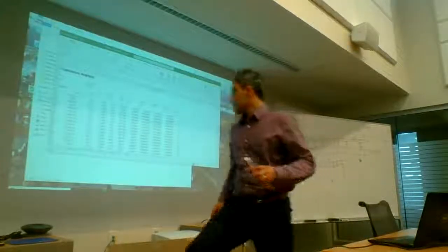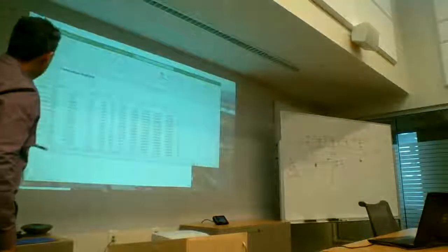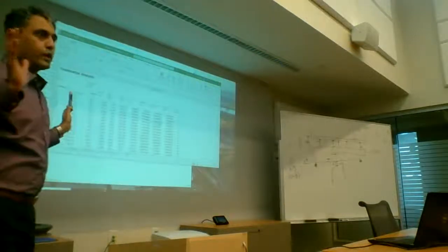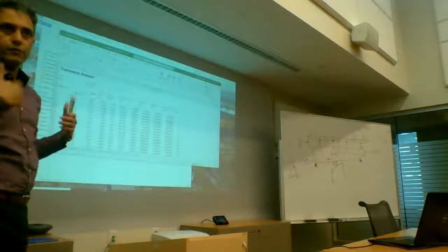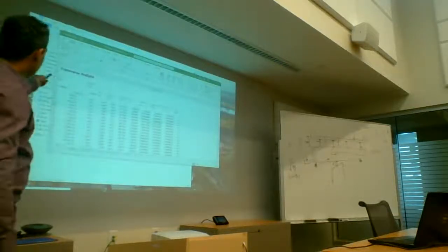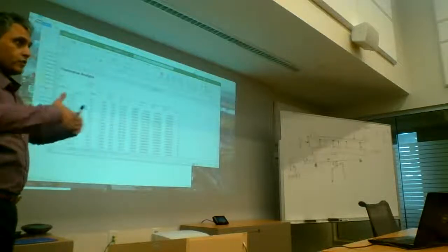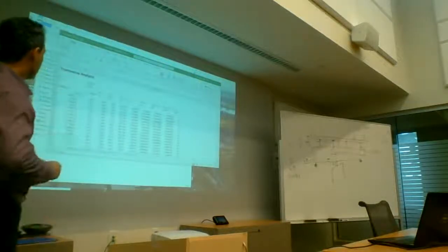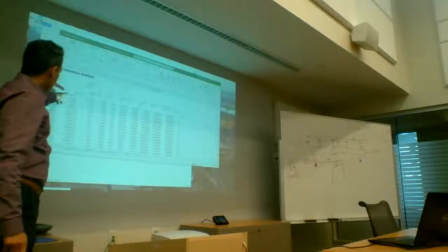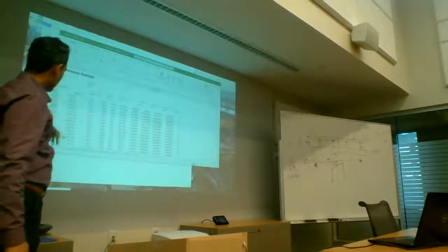So what I've done is I've taken a lot of sections through my bridge, and my spectral acceleration is 0.8. I've just assumed that for elaborating this thing. And now my P naught, which is that initial load to get my stiffness, is 10 kilonewton per meter. Okay, so I have my west abutment at location 0, and then I divide it up into a lot of segments.